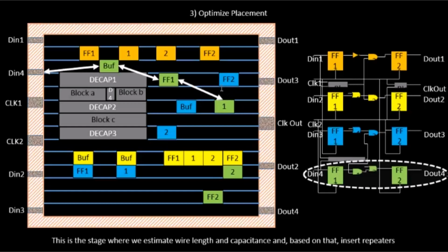So there is a crisscross, but we will find a way to fix this in the routing stage, where we take this connection from this point to this point in a separate layer, let's say metal 3, and we take this connection from this point to this point in metal 4. Currently you can think of it as different layers.